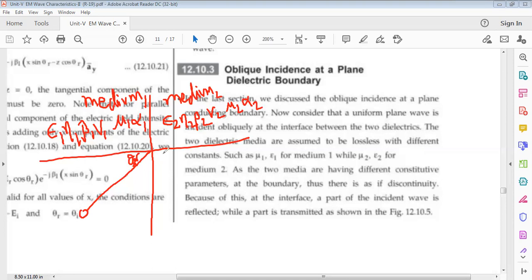The incidence beam, and there is a transmitted beam also, with an angle of theta t, and a reflected beam with theta r. I'm not considering which one is the E_i or the H_i function here; it depends upon E_i and H_i being vertical polarization and horizontal polarization. Medium 2 is also a dielectric medium, which means the transmission coefficient is not zero. Got it, madam?